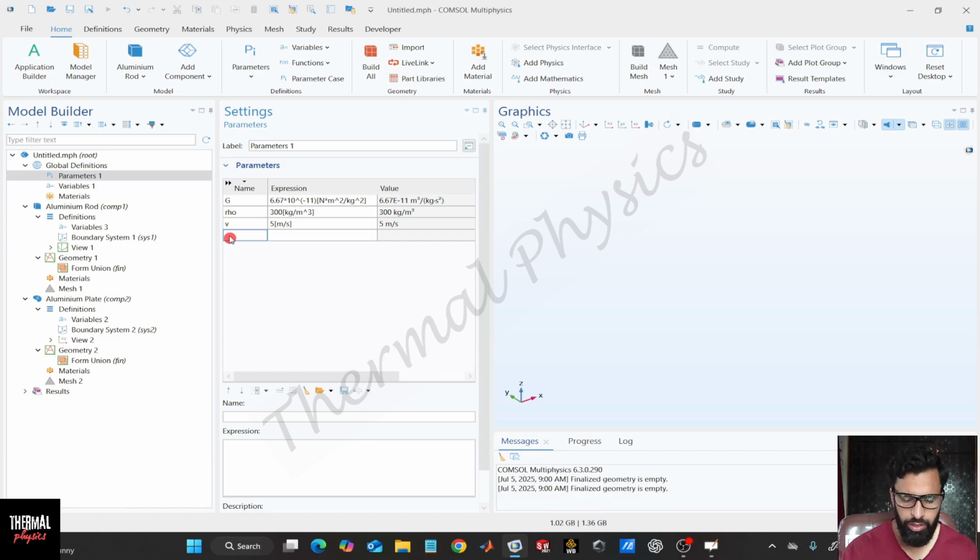Then we use another parameter in the Reynolds number, L, the characteristic length. Say it is 0.05 meters. So we have 0.05 meters. Then we use the mu value. Say the mu value is something like 0.3 Pascal second, Pascal into second, close. See, we have Pascal second.